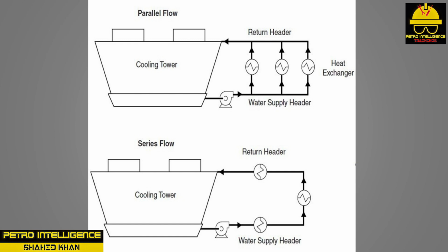cooled. A centrifugal pump sends the hot water to the top of the tower, where it enters the water distribution header. The hot water is distributed evenly throughout the tower, where much of the heat it had gained is given up in evaporation. The cooled liquid is recirculated back to the heat exchanger and the process loop continues.